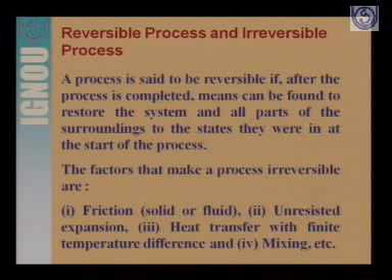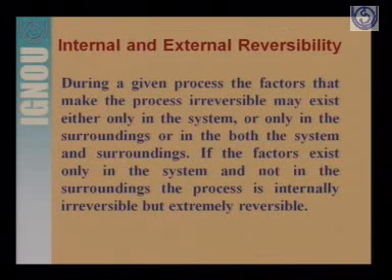But in a thermodynamic system, let us first find out what the causes of irreversibility are. That is friction, solid or fluid, unresisted expansion, heat transfer with finite temperature difference, and mixing, etc. These are the causes that make a process irreversible. And our basic aim is to reduce these factors, so that we come very near to the reversible process.